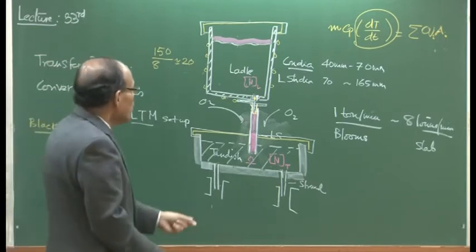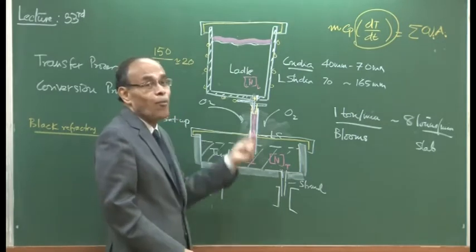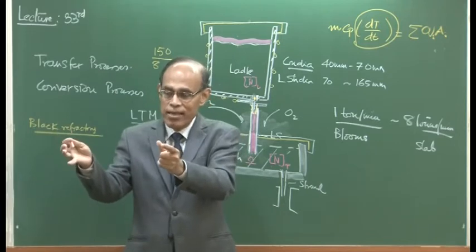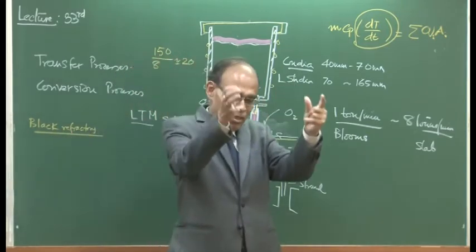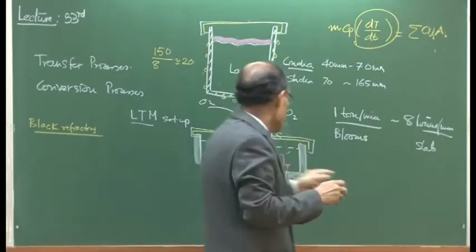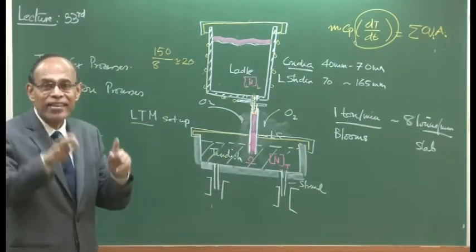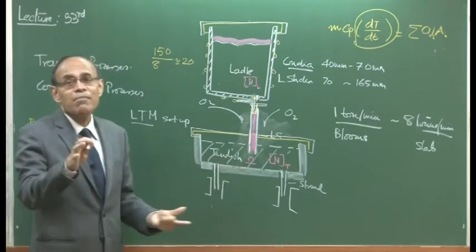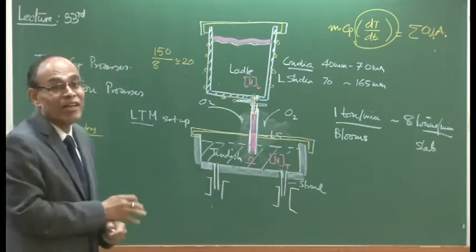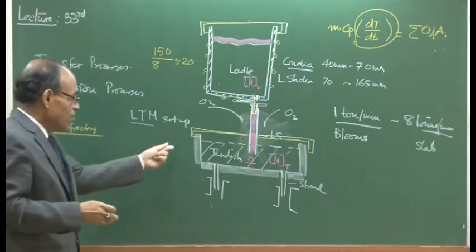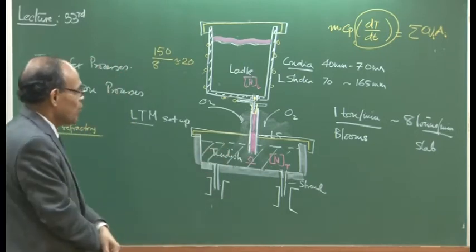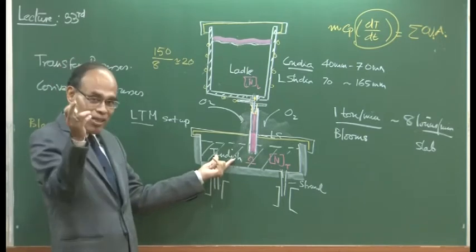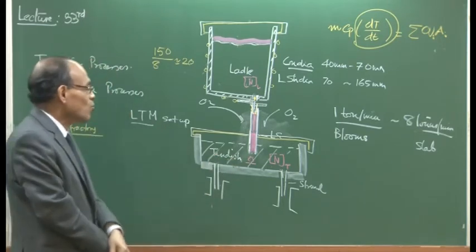So, now when you have opened the lid, this is called ladle opening. Once you have brought that ladle after the VD, and the holding period is over, you will lift the ladle and bring it onto the turret just above the continuous casting tundish. At that particular moment, what happens? The tundish is hot, it is preheated. In steel making, in no reactors is molten metal going to be transferred into something cold, otherwise there will be premature solidification of molten steel. The tundish is fired before, at around 1100, so they know at what time the ladle will be coming, and accordingly the tundish is preheated.